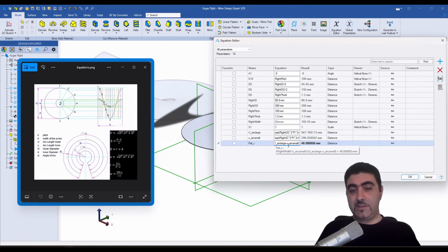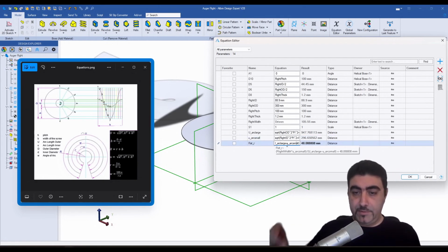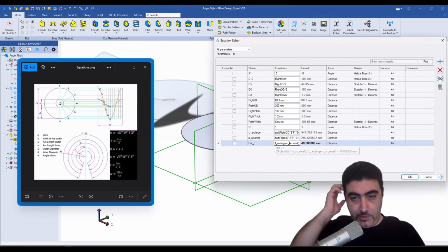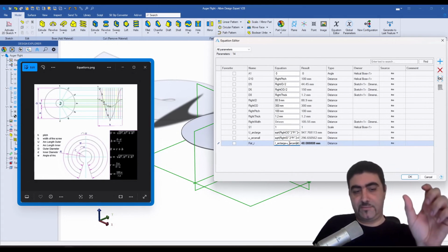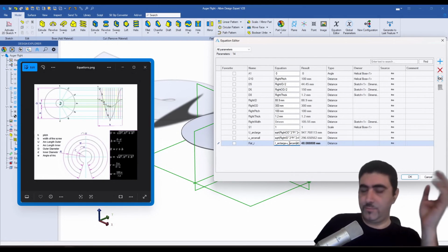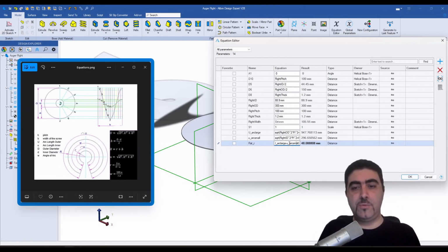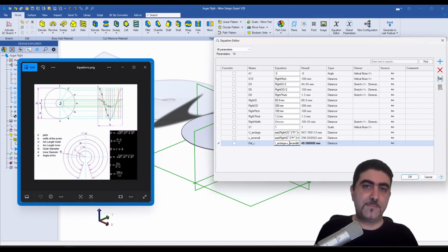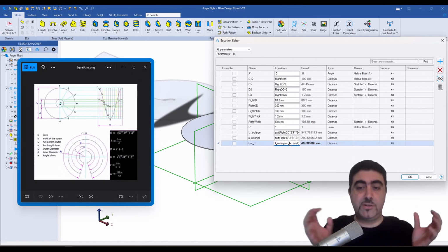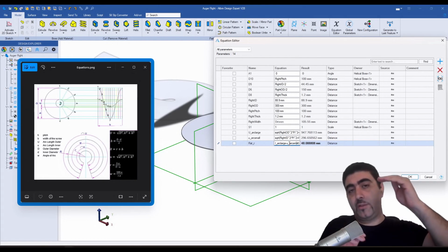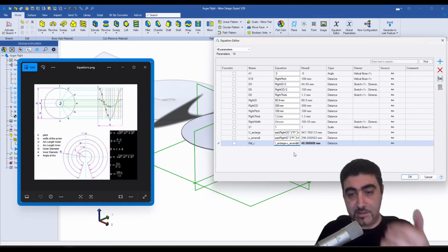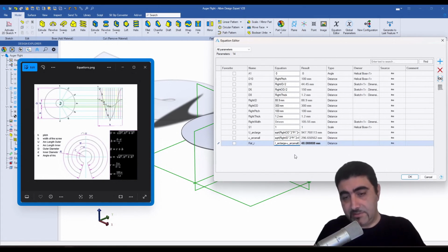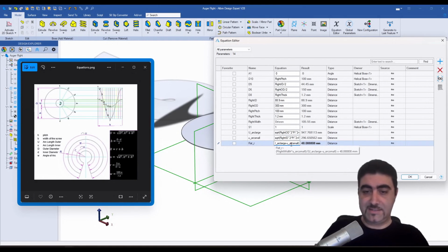So the way this works is you see in the pop-up the equation here: you multiply two distances on the top of that fraction and you get a distance squared, which is area. And then you subtract two distances, and the subtraction of two distances is still a distance. So on the top you have distance squared, on the bottom you have distance. So the result comes as distance to the power of 1. That's why it accepts it.